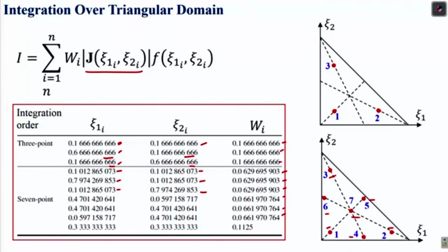Now this is how this Gaussian numerical integration technique can be applied, and this is very useful in our course, because most of the time whenever we apply finite element method, we need to integrate the weak form over the element. We will use this technique because most of the time our shape functions are polynomial.